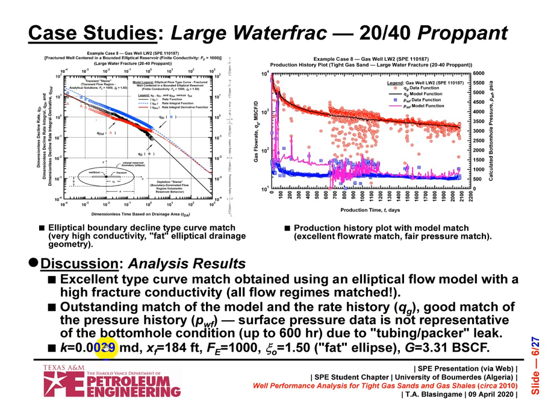In this case, the permeability is a bit lower actually. The fracture half length is a little bit higher. It is a much higher equivalent conductivity of the hydraulic fracture. The FCD is 1000. And then the ellipse this time, because of the lower permeability, is fat. It's almost like a circle, or it's approaching a circle. And then the gas in place for this well is much higher. So even though the permeability is smaller, the treatment was much larger.